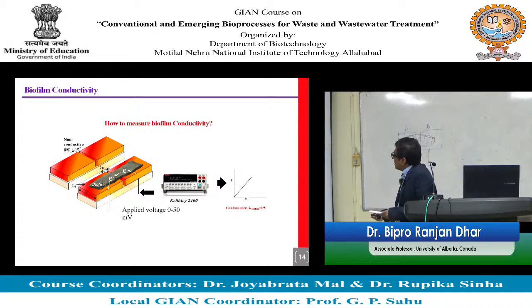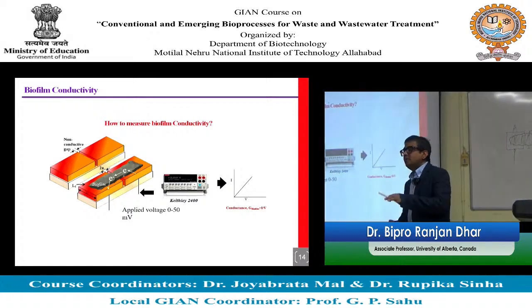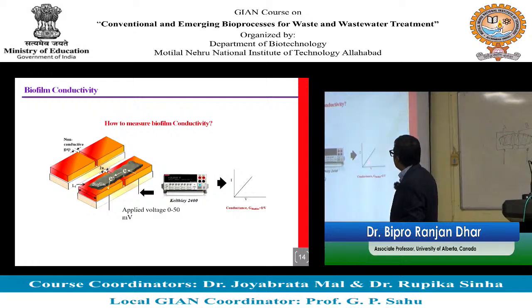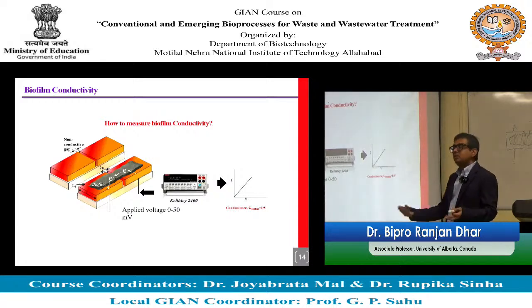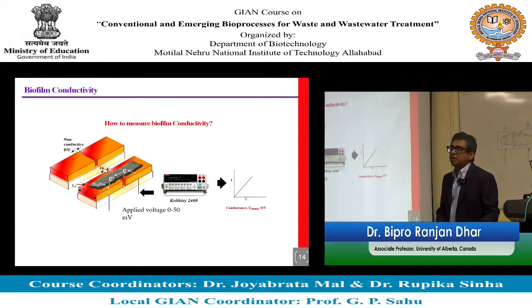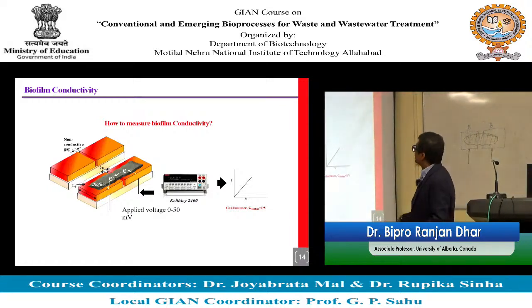They applied a small voltage and found a very perfect ohmic response between voltage and current. That confirms that the biofilm is conductive. If you know the biofilm thickness, then from this response using Ohm's law you can estimate conductance, and based on that, using an equation, you can calculate conductivity, which is in millisiemens or microsiemens per meter.